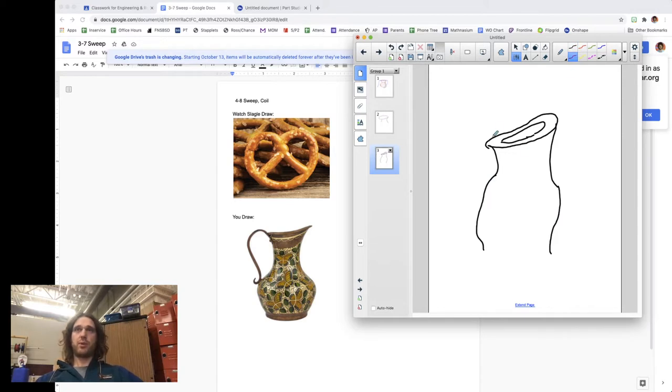And then for the sweep, you're going to create a sketch in that same plane, but it's just going to be a spline, and that spline is going to come down like this. It's going to come to the bottom, and then it should be S-shaped. It should have both of those bends. I'm looking for both of those bends. Okay, and then you'll create a plane right here at the end of this point. You're going to draw your circle or an ellipse. I think an ellipse is actually easier. So I would make it stretched out like this.